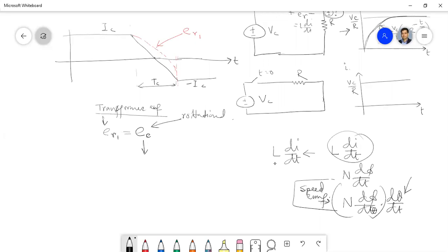So how is this rotational EMF generated? Generally, as I have already pointed out, in the commutation place there should not be any rotational voltage in the coil, but this reactance voltage initiates that rotational voltage. So we should have some rotational voltage in the place of commutation to counter that. Therefore we will allow some flux, or some rotational EMF, at the commutation place.